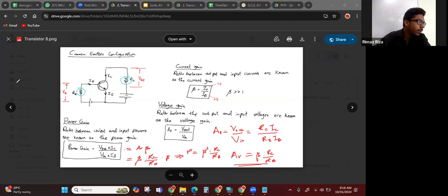You had to consider a complete circuit connecting the input and output. So I can draw like this. Here, if you consider the current in this loop, through the RB it's going in this direction. But through RC, it's not in this direction. If it were also going in this direction, then the signal would be non-inverting. But we can see the IC is in the opposite direction. Therefore, current through the RC is in this direction. Therefore, here the signal is inverting. The output signal is inverting.